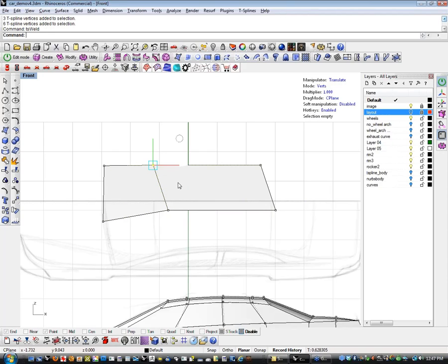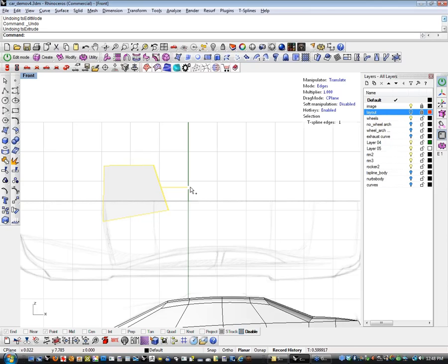It'll weld anything that's coincident on top of each other, and I'm back to 1. If you have stacked verts like that that aren't welded, it will throw a crease through your model. There's no way around it. So the way to do that is if you Alt-drag an edge and don't like where it is, undo it again. Because what happens is when you hit the Alt key and you click on this and drag, you've made a face. You can see it there.